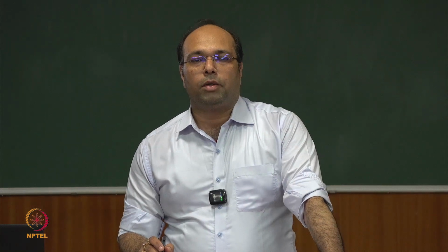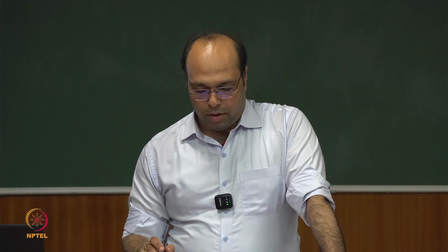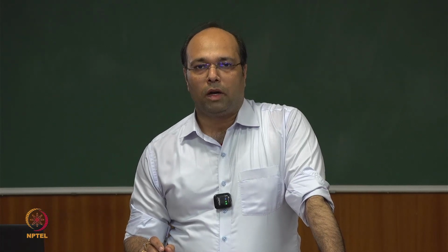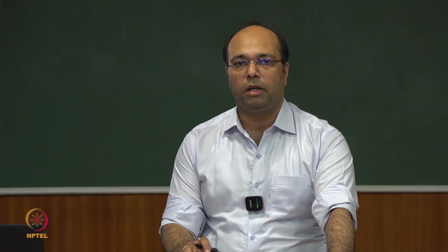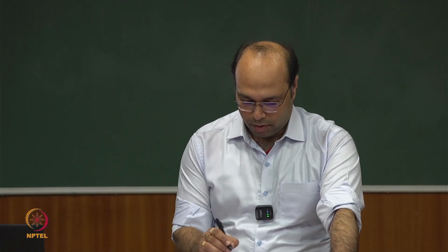Hello all, welcome to this course, and now let us proceed with the modeling and control of induction machine. Particularly we'll be dealing with the squirrel cage induction machine. So till previous lecture we have seen how we can make use of the frames of reference which are related to the stator and rotor, and then synchronously revolving frame of reference for modeling of the permanent magnet synchronous machine. Now we'll make use of little bit extended equations and little bit extended frame of reference for the induction machine, and then we'll be proceeding with the model.